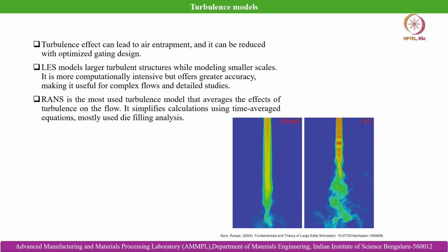Our objective in solidification is this: in die filling, the melt filling the component cavity is not only subjected to shear strain rate, but is also continuously losing its superheat. If we are talking about an alloy, it is continuously going below the liquidus temperature, at least in certain locations of the flow front.